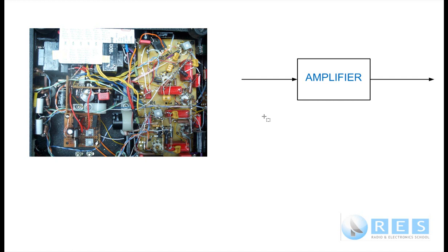That's not good. And that's called a parasitic oscillation. I've brought a diagram of a transceiver that's very likely to have parasitic oscillations. Have a look at how this device has been built here, and it's a rat's nest of wiring all over the place. It's pretty messy. Well, all these little bits of wire have inductance. There's capacitance between all these little bits of wire. There are stray inductances and capacitances all over this circuit.